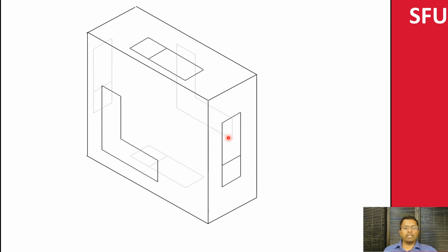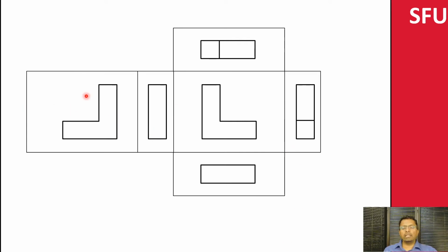Then I open the right side view, so that ends up opening this way, and the left side opens up this way, the top opens up to the top, the bottom goes to the bottom of the drawing. And there is another thing: we have the backside view, which ended up on the tail section over here. So this looks like a plane going from left to right. You know, it's a kid's analogy.